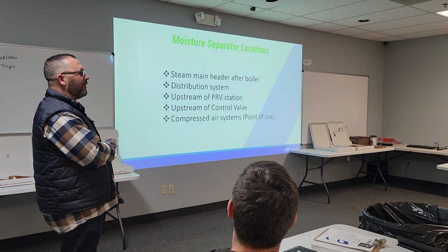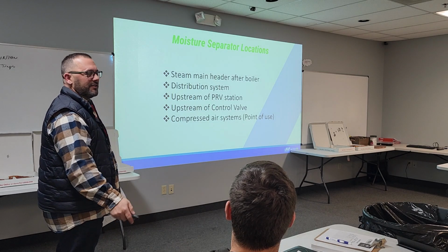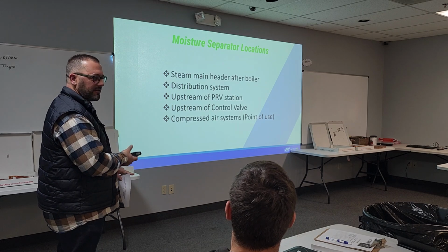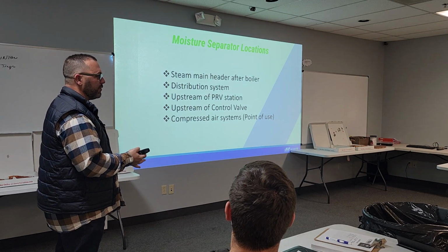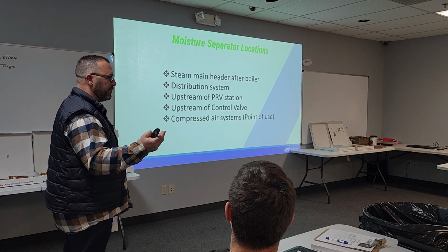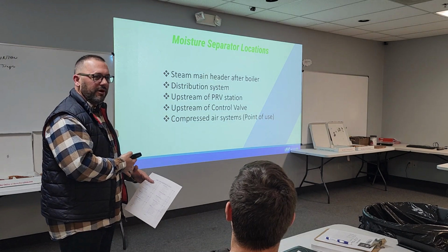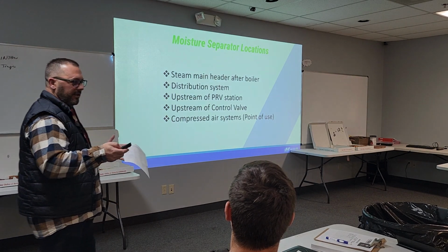The thing that's tearing all the valves up and tearing all the equipment up is the moisture. It doesn't matter whether it's Spirax Sarco or Watson McDaniel or Armstrong. Pick a manufacturer, they'll actually double their warranty on the control valves and PRVs if you put a 100 mesh strainer and a moisture separator in front of it.